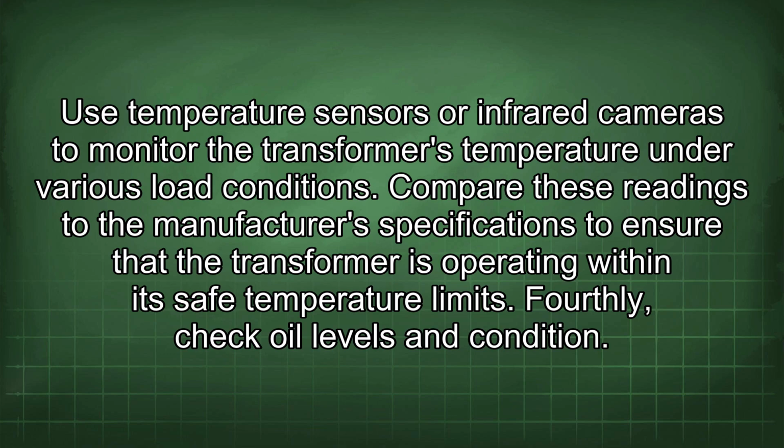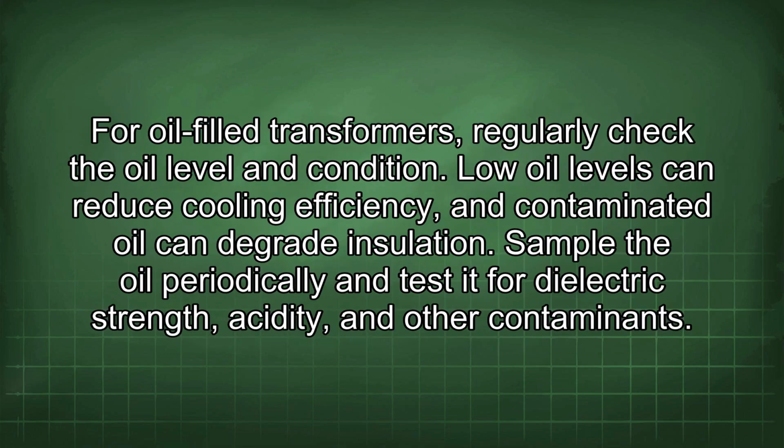Fourthly, check oil levels and condition. For oil-filled transformers, regularly check the oil level and condition. Low oil levels can reduce cooling efficiency, and contaminated oil can degrade insulation. Sample the oil periodically and test it for dielectric strength, acidity, and other contaminants.